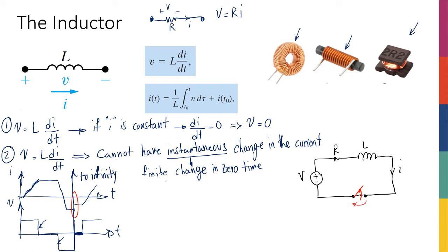So you're going to have electrons, or basically electricity carriers, whatever you're comfortable with, jumping over this gap, and that's why you will see those sparks. You will see something called arcing. There's an arc between the two sides of your switch, and that happens for a very short amount of time until the current of the inductor comes to 0. But you're going to see that.